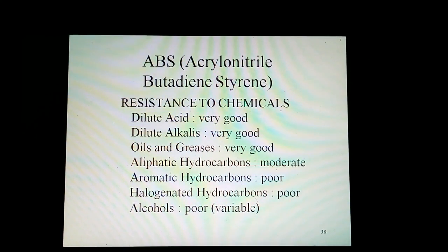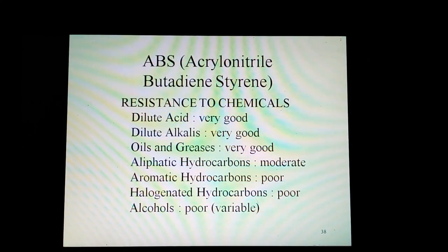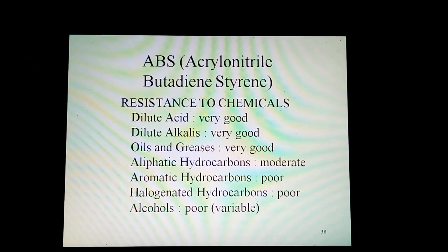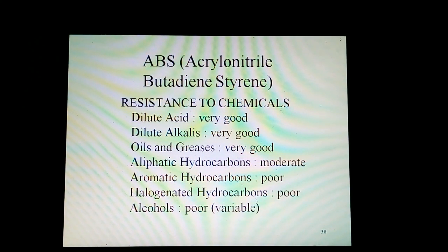Resistance to chemicals. For dilute acids it is very good. For dilute alkalis it is very good. For oils and greases it is very good. For aliphatic hydrocarbons it is moderate. For aromatic hydrocarbons it is poor. For halogenated hydrocarbons it is poor. For alcohol it is poor but varies.